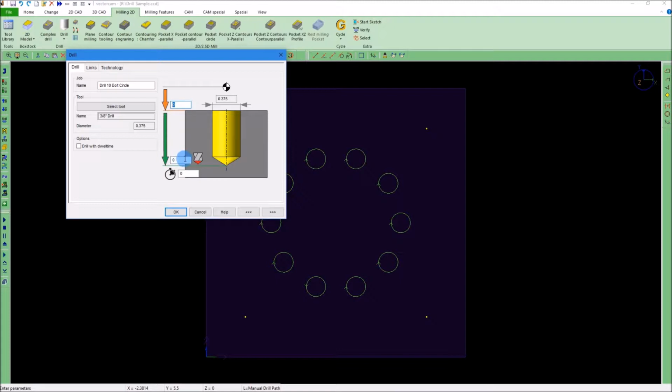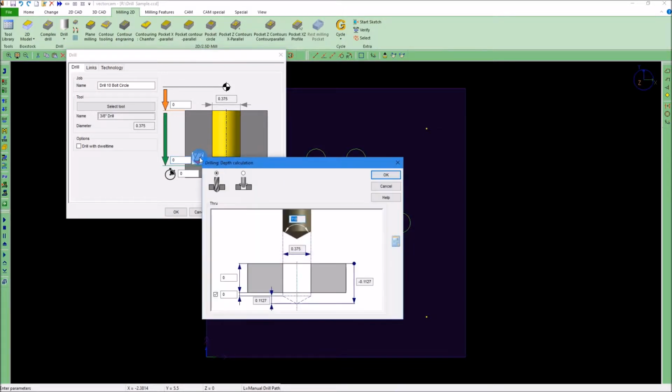This value here is what will be the distance to the bottom of the drill bit from the reference we gave it up here. There is a wizard to help calculate this here. This wizard is to help you do the calculation, and the settings in here are not stored. To use it, put the material thickness in this box. Please note that this is only needed if you need the calculation to compensate for the material thickness. However, in this case we do not need to do this, because our reference is at 0, which is also at the bottom of the material, so we should leave this 0.